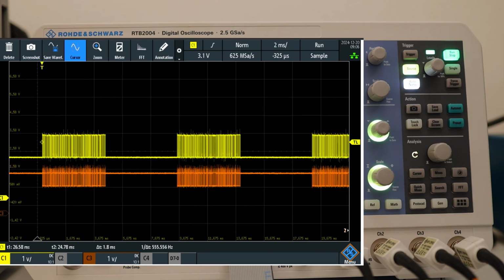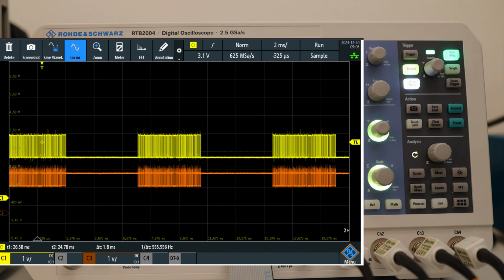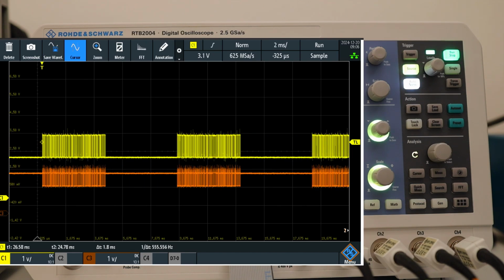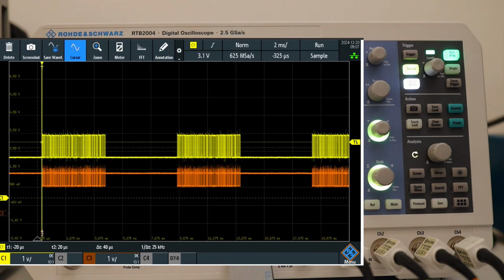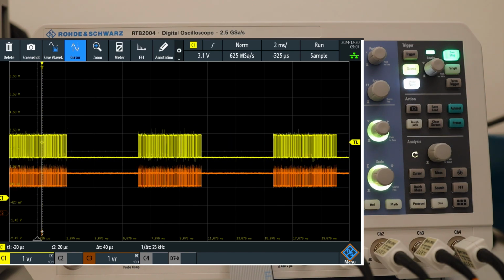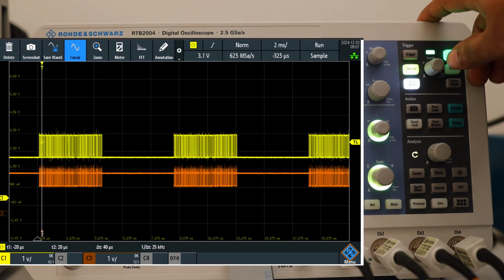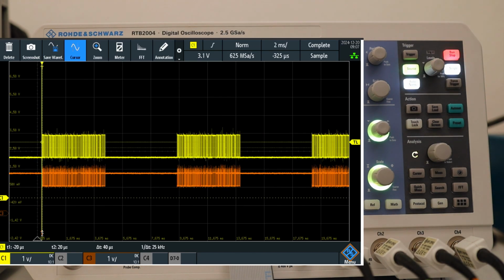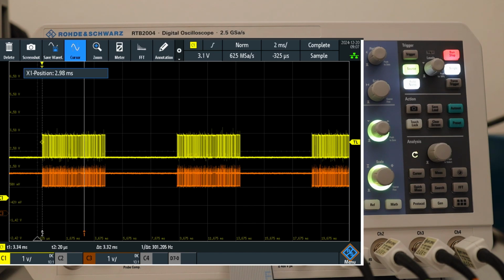Right now you can see on your screen the signal is quite flickering, because it's set for edge trigger, and normally oscilloscopes are set to edge triggers. They will try to detect the edge and try to find a good stable trigger with that. In the case of a digital signal, it's mostly not possible. You must understand that when I'm moving this trigger, this cursor, you can see these are all valid trigger conditions. There are many rising edges, and that's why you see the signal flickering.